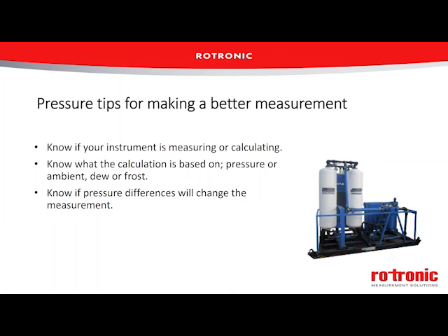If you're measuring dew point in a compressed air system, which is a closed system and the pressure can vary, then absolutely you have to be aware of where you're measuring the pressure. Are you measuring the pressure in the line? Or are you measuring with a sample off of the line that's actually expanded? If you're doing that, you've got to make a calculation to get the right dew point.